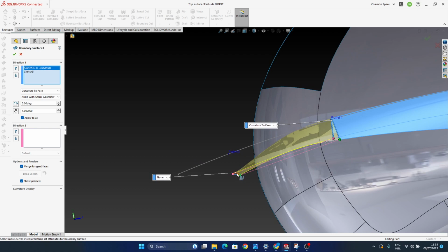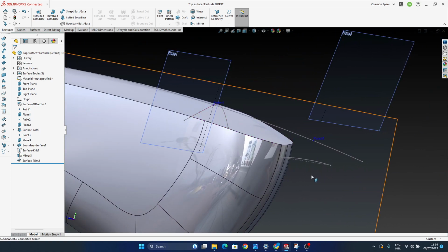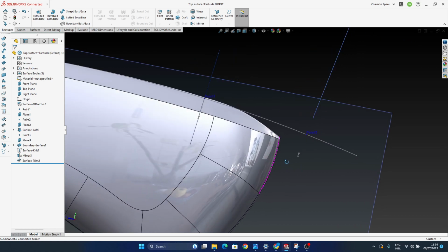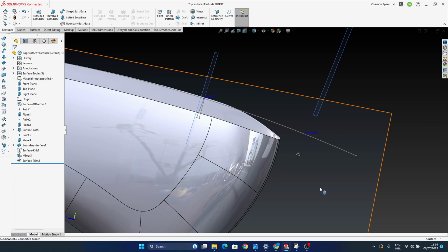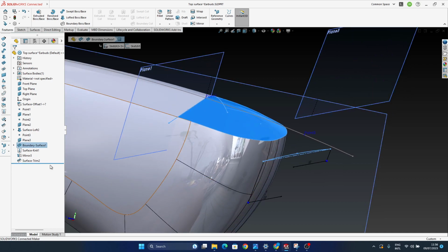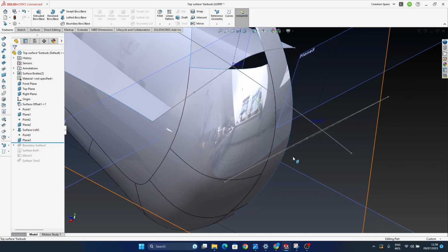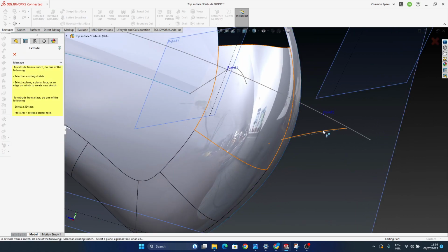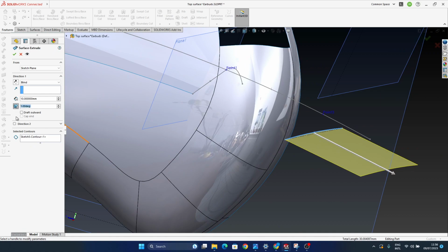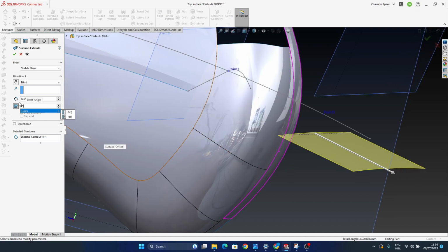We could also create a surface at an angle in here. And let's try to do that instead of going straight in contact with this sketch. Let's try to create an angled surface with which we can adjust this profile here, right? So I'm going to go here like that. And I think if I'm selecting this and I say I want it at an angle, I think I can say, I don't know, 45 degrees.